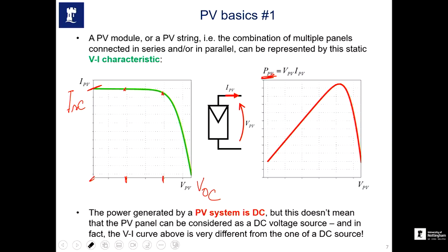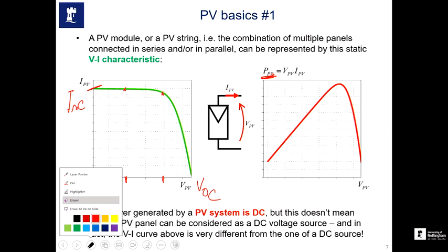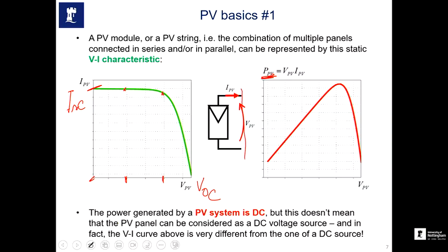Because at that voltage, which in this case is at this point in here, we get the maximum out of the PV. So that's why, before the inverter, we connect a DC-DC converter, okay? DC to DC. That DC-DC converter, first of all, generates a certain voltage in here and also makes sure my VPV always stays at this point, VMPPT, okay?